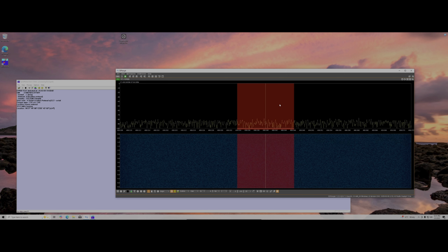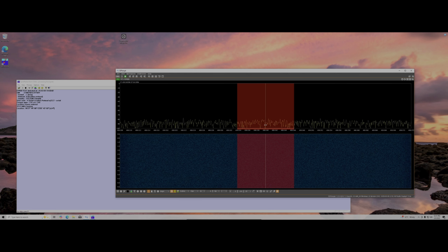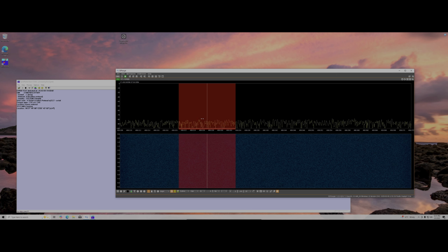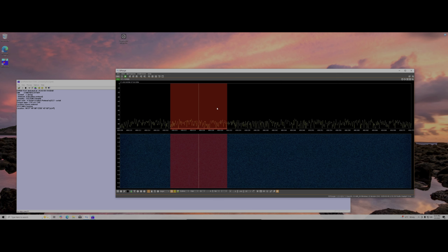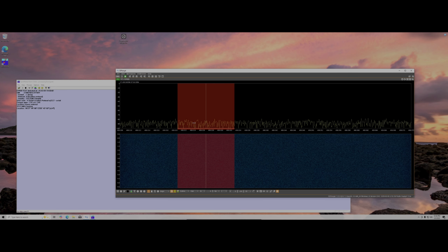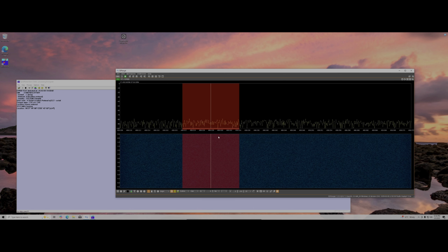So if you're replaying your ELT signal, or if you're testing your ELT and you're just not getting any population, what you can do is you can just tune this over to here, right? Kind of capturing those lower frequencies, and you can try to pick it up doing that. So you do have tuning control here as well. Apart from just the spectrum you can see, you can narrow it in. And this is what it's actually outputting to your speakers, just the stuff in the red band.